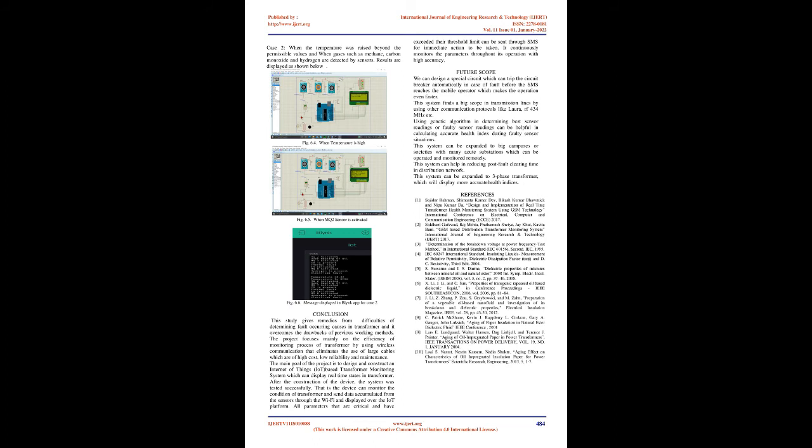The same output is also transmitted through the Wi-Fi module to the Internet server and then to the mobile application Blynk, as programmed in the Arduino. Data will be saved and can be used for further analysis. The GSM modem is used as a short message server device that transmits parameters as an SMS. By the use of software to store and perform dissolved gas analysis of the measured data, information on the state of health of the transformer, and alarms raised when measured values exceed appropriate limits, can be provided to the operator.